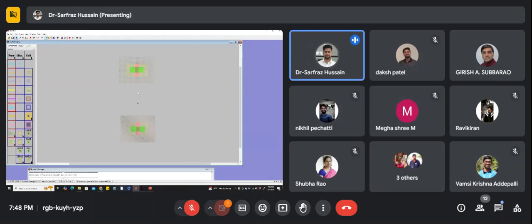Another thing is, what is going to be the size of this PMOS and NMOS? Remember the size of PMOS. Just press Control I. The width of the PMOS is 2 micro, so we'll put 10. Length, we'll keep as 5. Apply it. So this is 1 micro of length and 2 micros of width.